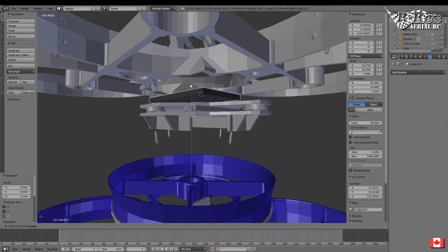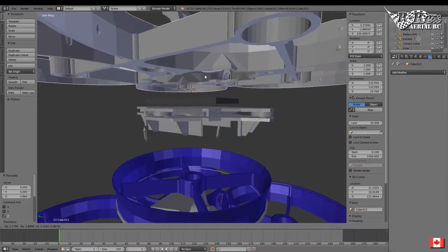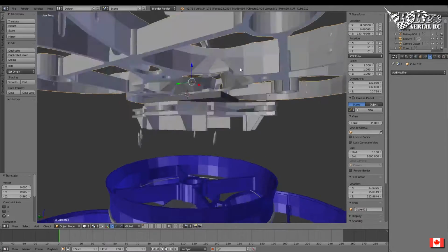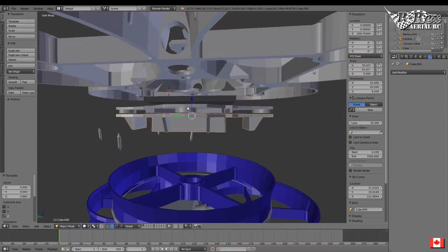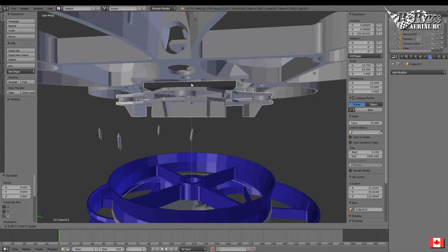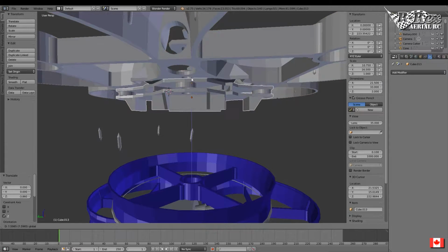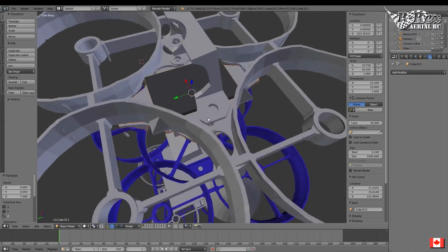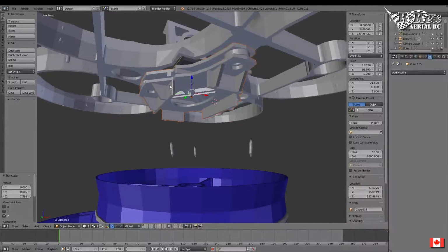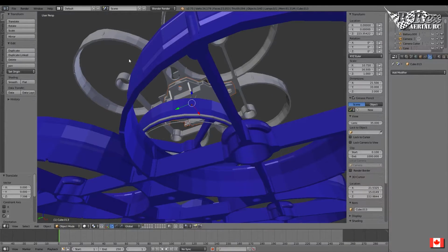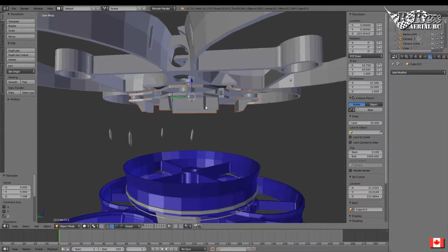So to make that all work, what I did is I added these little points here so that they cover the flight controller and there's nothing in the way. Airflow is being directed around the flight controller, and that all just fits up inside when you bolt it all together. You'll see there's your clearances. It's pretty tight, but this thing has proven to be extremely strong, and I like doing it this way.